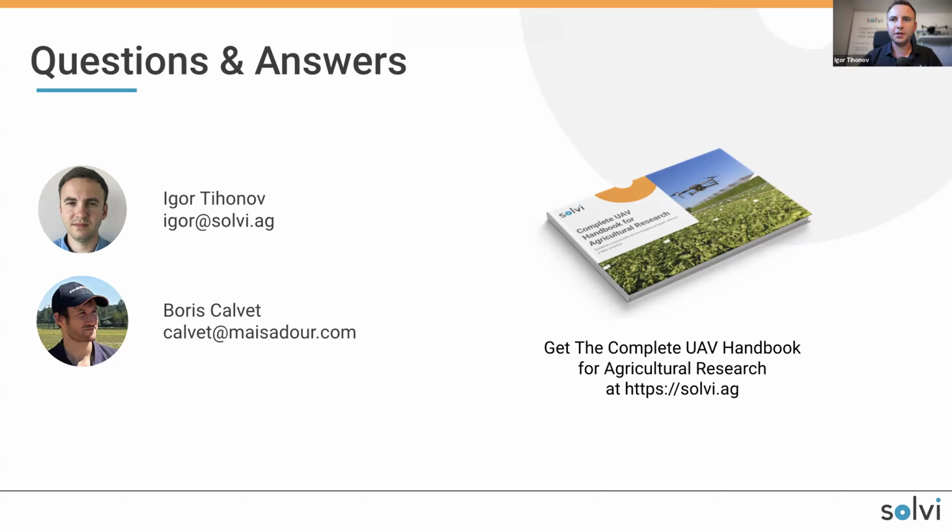Right. I think Wingtra drones, the one that I had in one of the slides, have support for PPK, and I think they also provide the software for post-processing of the imagery after the flight. Then you would use that workflow, and once you post-process the images, upload them for stitching.